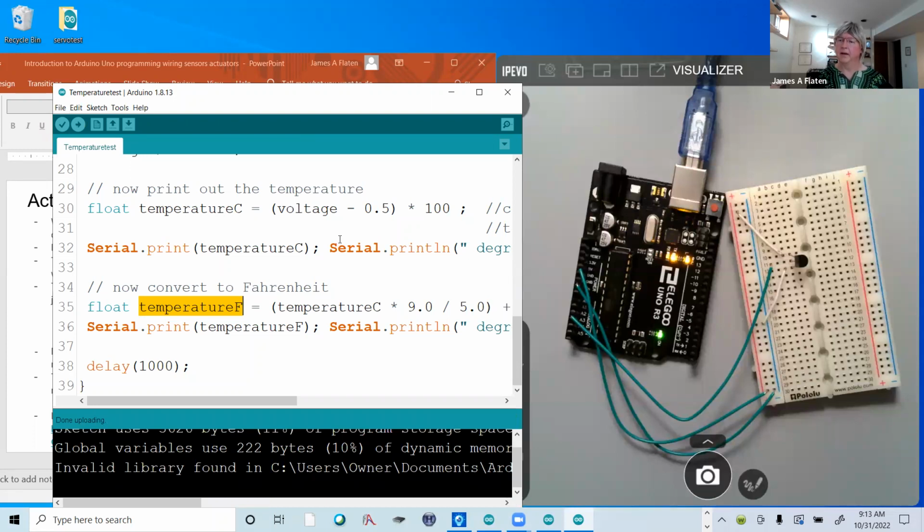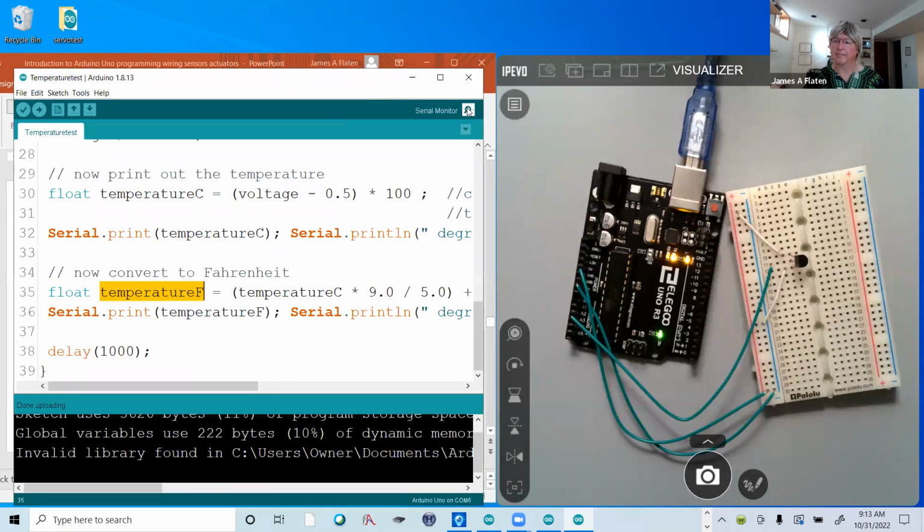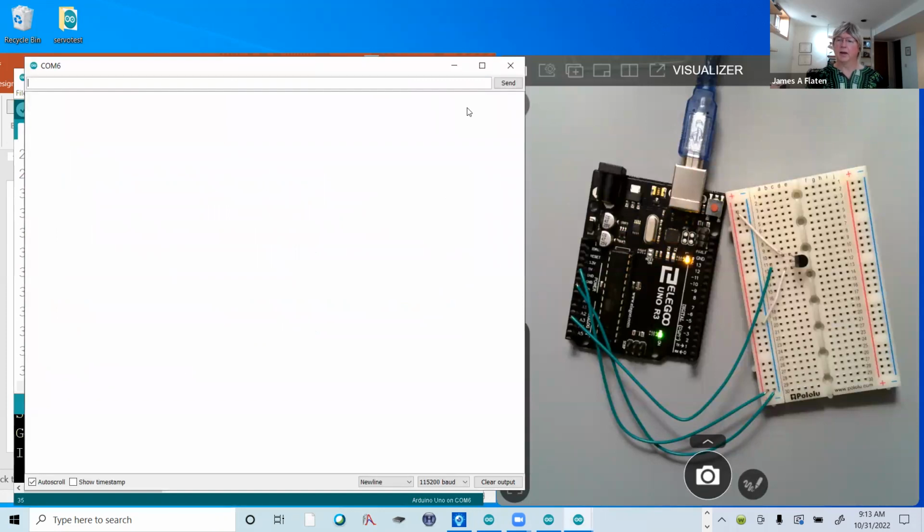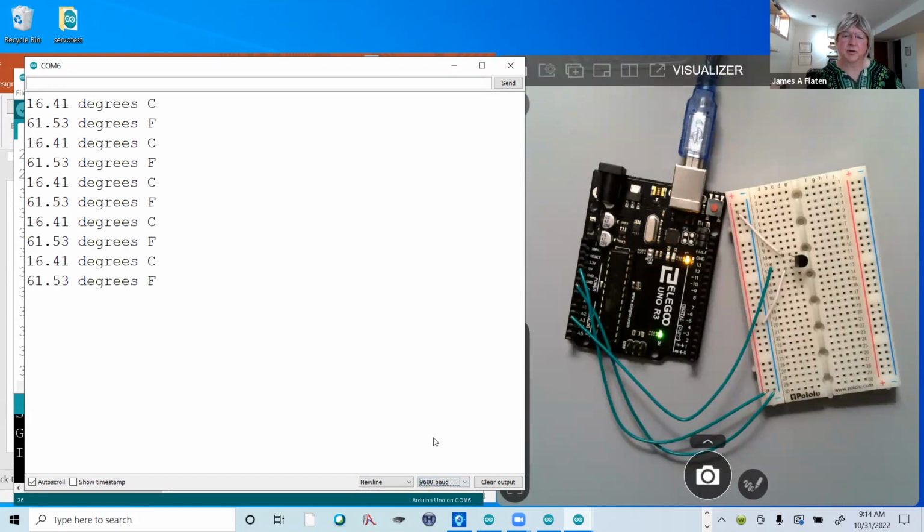This is good. Now I'm going to open the serial monitor, because that's where it was supposed to be putting the answers. Here's the serial monitor, and nothing shows up. This is a sign that there's probably a disconnect between the rate with which it's talking and the rate with which I'm listening. And sure enough, if I look down here, I can see that it's listening at 115,200 baud, but I was actually transmitting at 9,600 baud. So let me try that instead. So now that I have 9,600 baud, now the messages are interpretable, and it comes in at 16 degrees Celsius,